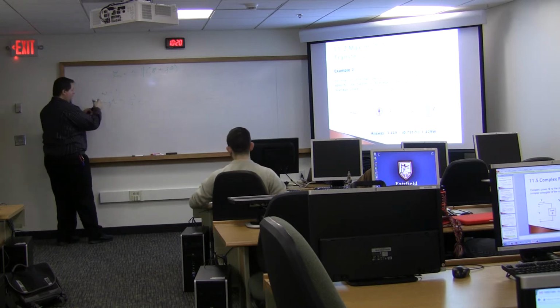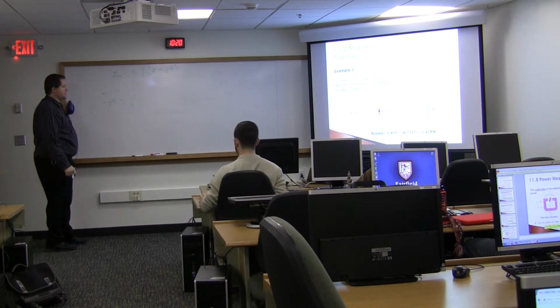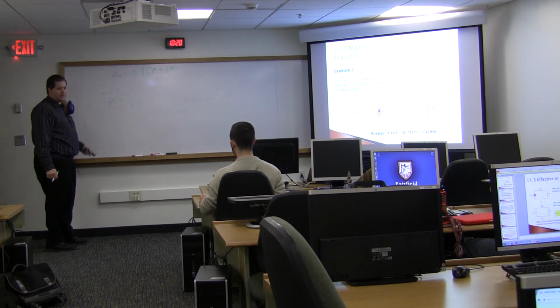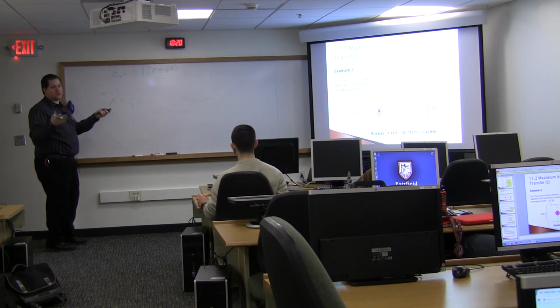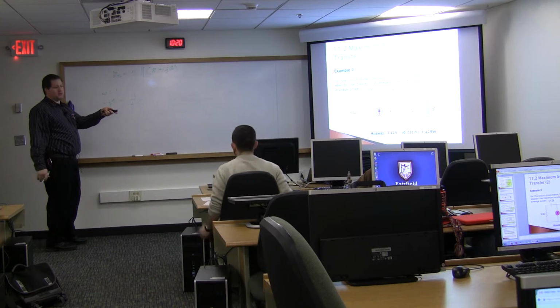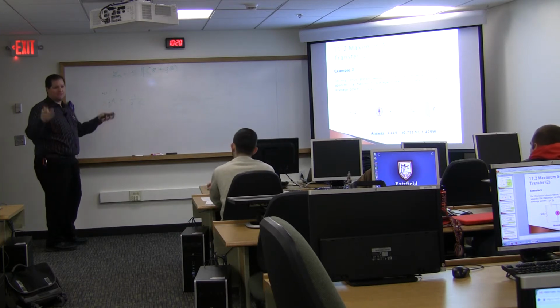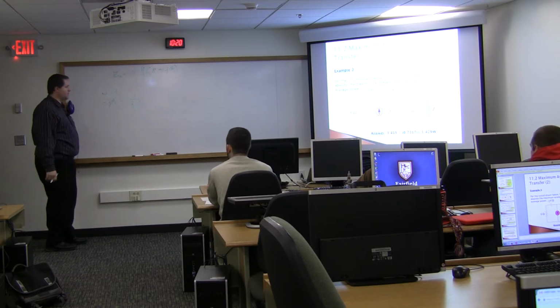I got you. And now I can just solve for C. So unfortunately, you do have to do a little bit of math. It's a little simpler on the inductor because it's just j omega L. So if I assume omega is 1, then L is 10, right? But with the capacitance, you've got to flip it over.